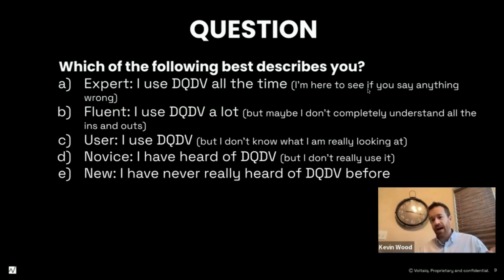So obviously, as you cycle batteries in the real world, there's a lot of changes, but all of those are galvanostatically controlled because the current is being set, right? Pretty much the only time, I'm sure there are probably some exceptions to this, but the main time that you're going to see that voltage control, that potentiostatic control, is going to be during the very final step of the charging phase. And sometimes during a tap charge, during the formation process, during battery manufacturing.